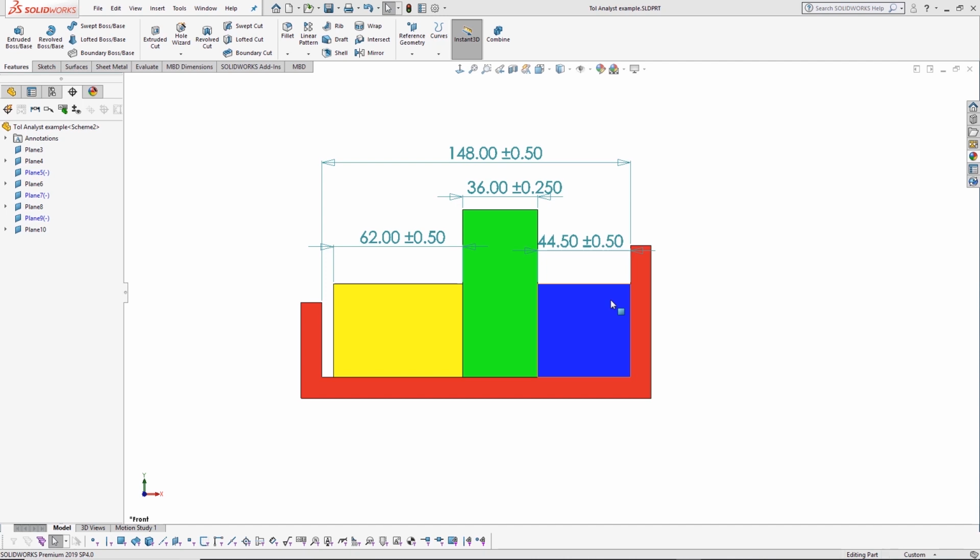This means that when you actually come to assemble your finished model, it might not fit. You might find that the tolerance that's been stacked up through the components will make it either too big or too small, and you'll end up with a slight clearance issue. Take this example on screen at the minute.